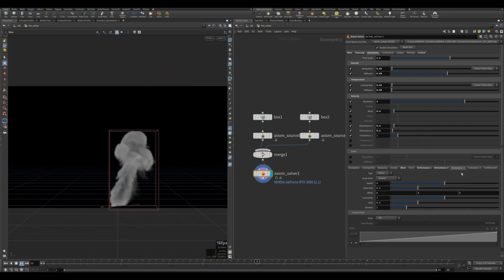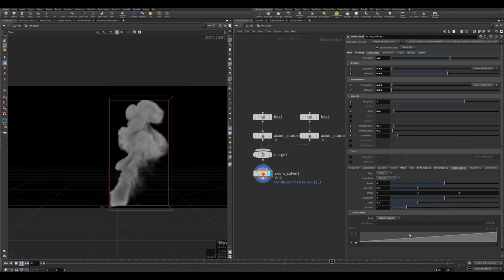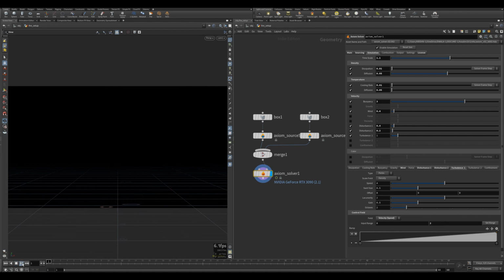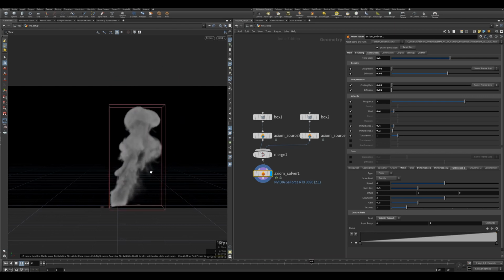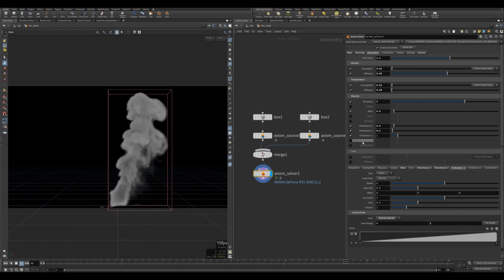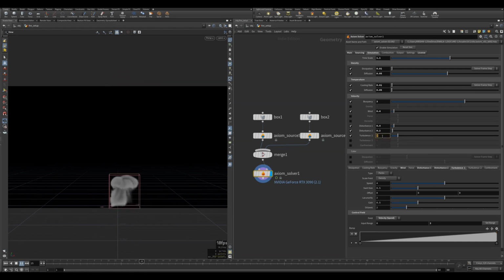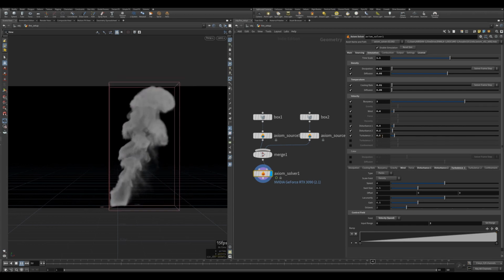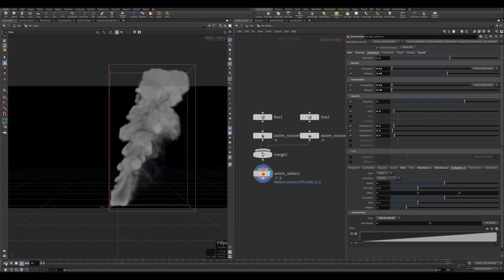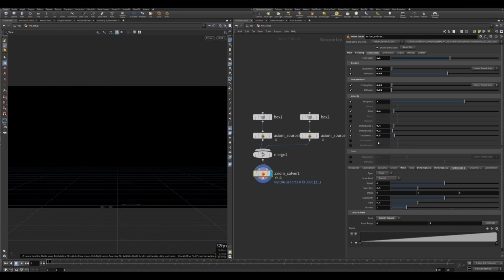With turbulence 1, I'm going to leave everything at default. I do want to affect the density. And the control field, again, velocity, and I want to change the input range to 0 to 2. You can see set range is 0 to 12 really, but okay, so there it is. It's affecting a lot at the moment. What I want to do is use turbulence 2 as the one that has a bigger impact. So this one, I'm going to change it to 0.5, so it has less turbulence, and turbulence 2 will have significant impact, or at least I'll punch in a higher value to this one.